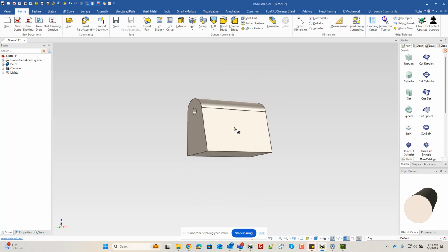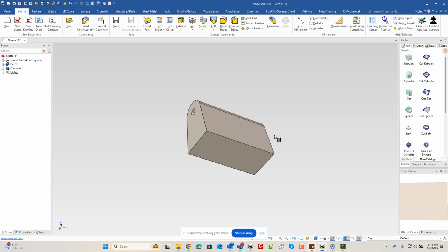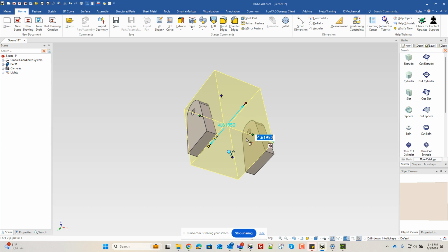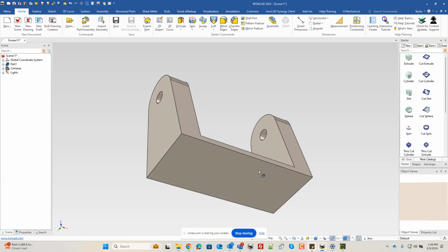Next, we need to have a cutout here for the middle part. So I'm just going to drop that on the bottom in this case. I can just pull this up to cut through, and then I can pull the side here. We know the width of this is our inside width, which is 4.25 inside of there. And we know the bottom of this is actually the overall value minus 0.25. So we're just going to minus 0.25 there. Oops, forgot to put a minus in that. So click that. Minus 0.25. There we go. So that will give us our cut there for our shape.